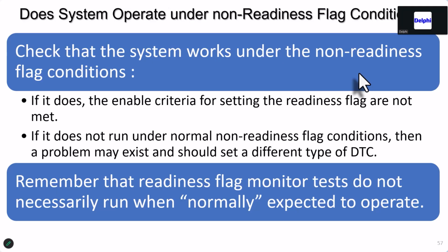Okay? And flow. EGR, purge. You get in your driver's seat, you're wondering if the purge works. You rev it up to 2,000 RPM in your front seat. You look at your scanner. The purge opens up, the FTP drops. You know the purge opened. You know you met the criteria to open the purge.